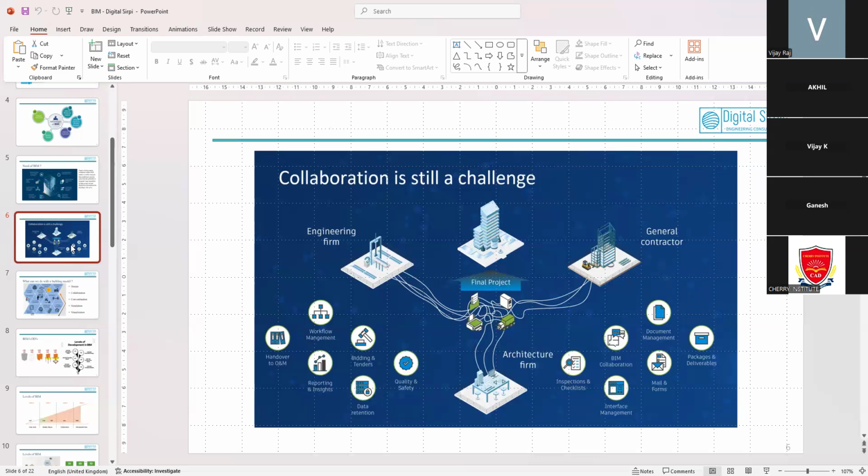But in BIM, we have to follow one standard called ISO 19650. This is a very major thing in BIM, to follow the standards. Using the standards, we maintain each and every project with the necessary naming standards, output and input registers, first time acceptance and first time rejection reports, and delivery reports, and everything will be coordinated under the ISO 19650 standard.